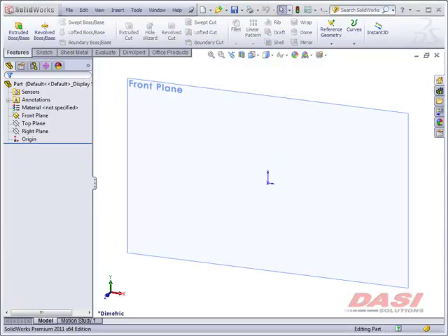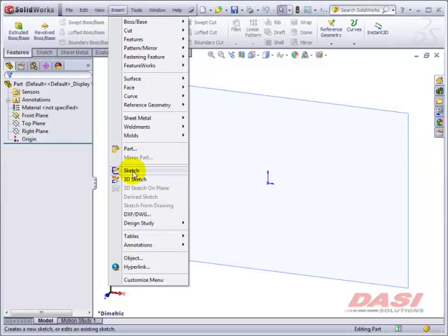Now that we see where sketches fall in the modeling process, let's show how to start a sketch in more detail. As this video will demonstrate, you'll see that there are many ways in which we can start a sketch, but I'll focus on just one of these ways for now. In our Insert pull-down, I will start a sketch by selecting the Sketch button listed there.